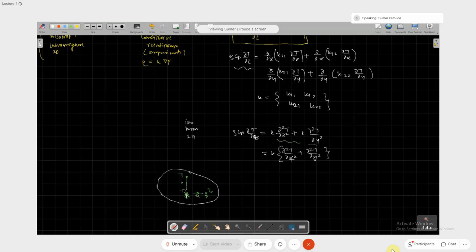And this third term is the diffusion term. This diffusion is irrespective of your movement. Suppose you are here and here, both without moving yourself, and you see a change. Unlike before, where you moved and felt a change while moving with this velocity, now assume you are not moving with any velocity, but you are present at two locations. Whatever you feel is without the effect of bulk motion. Here you don't feel any bulk motion, whereas earlier, while moving through this space itself, you felt some temperature changes and then finally T2.